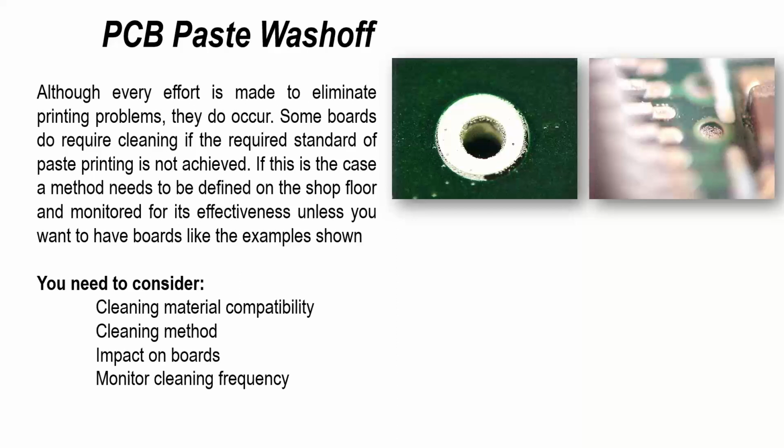But one also important thing is you must monitor the frequency. You don't want your screen printer operator, because of some frustrations with the quality of boards or the stencil, having to print and then clean off 50%, 10%, or even 5% of the boards he's processing. So you need a check, not as a check on the quality of the printer operator, but a quality of the problem. And it's good practice to keep a log of how many boards you're washing off.